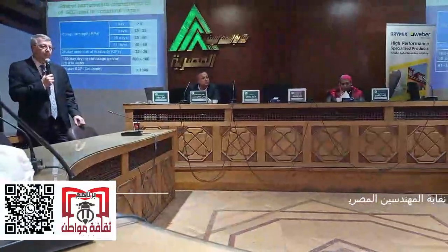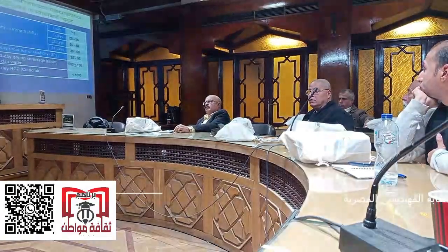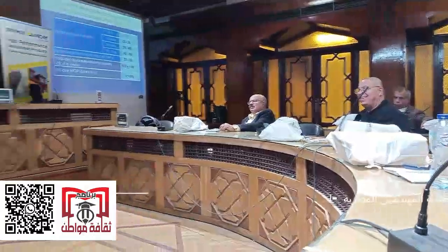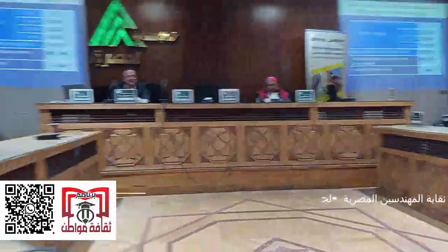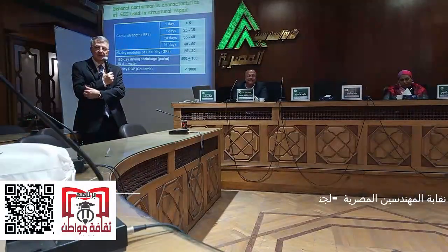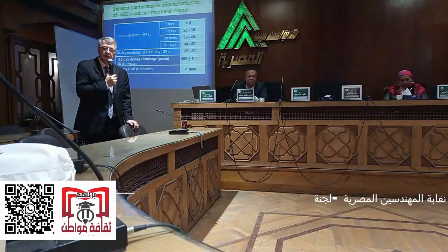In the Iconic Tower here, they used a compressive strength of 80 megapascal. And for the Tahya Misr Bridge, the strength was 100 megapascal. Wow. And by the way, I got 127 megapascal. High strength concrete, of course. Yes, fly ash. Not fly ash, silica fume. Yeah, silica fume, in this case like 6 to 7% silica fume, maybe.